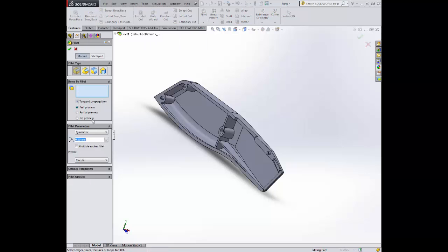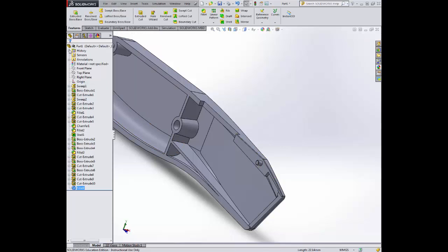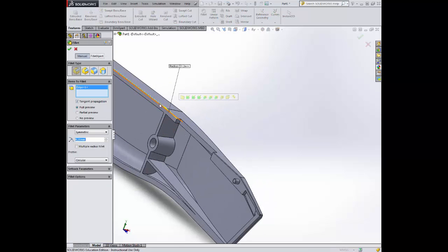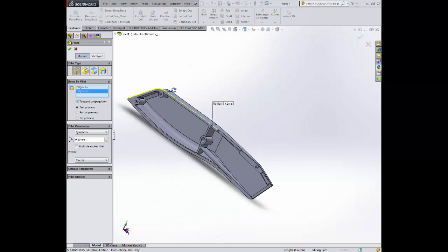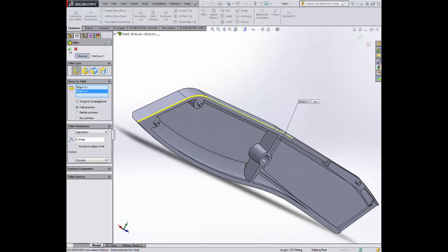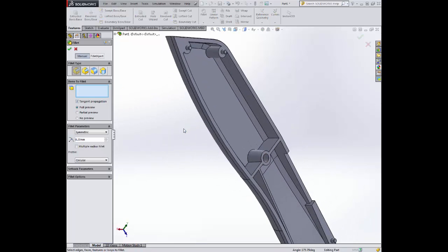Final thing to do is to fillet some of the edges to allow us to identify the split line. And there's going to be 3 different sections to this. So this line and this line, so the top edge. It's a 0.2mm fillet, so that's that one. Back to my fillet tool again. Again, choosing my lines in order. That's automatically chosen the others around the corner. Happy with that, 0.2. And then back for the last fillet.